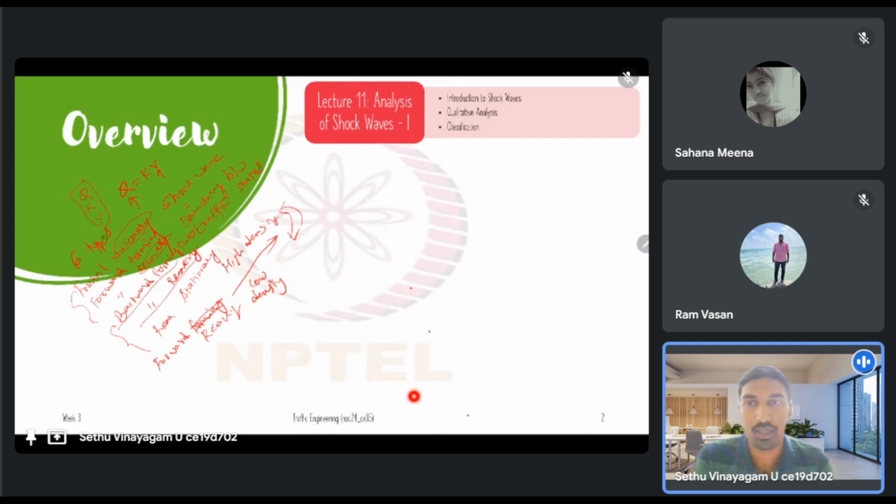So backward forming is that shock wave where the queue length grows, right? And backward recovery is the shock wave that will be reducing the queue length. Okay, and rear stationary, forward stationary. So these have zero slope. So they will be at a given location, right? So these are the qualitative ways of describing the shock waves.